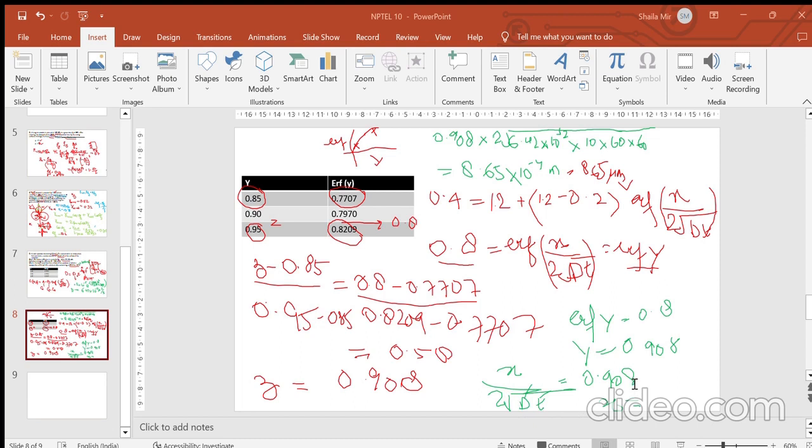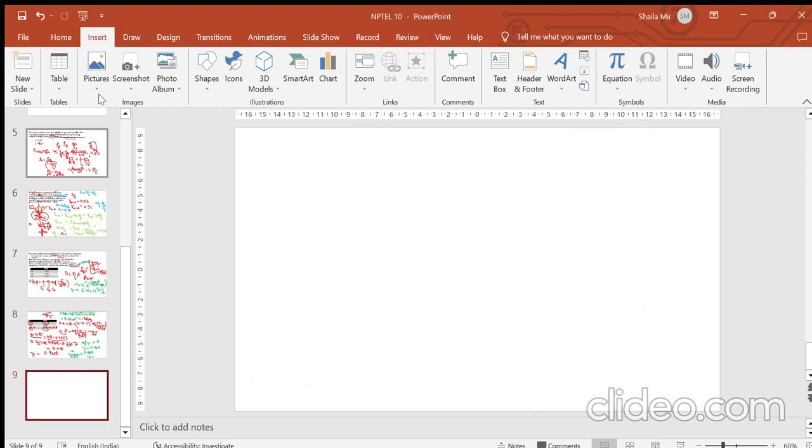Okay, you have a question about dislocation density. Actually, yes, any material will have certain defects in it. There are different types of defects: line defects, surface defects, and one of the defects is the dislocation. So if you have a material, you have a grain like this, and there are dislocations present in the material.